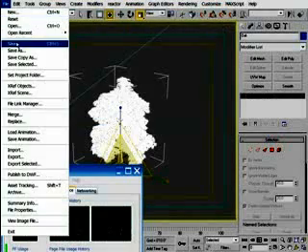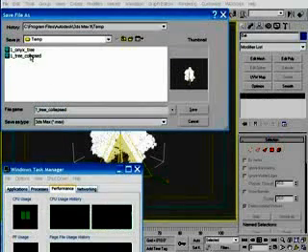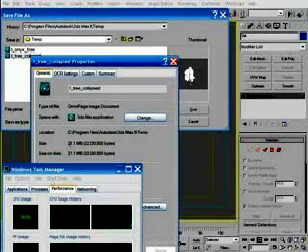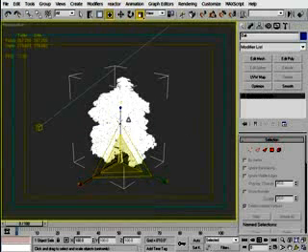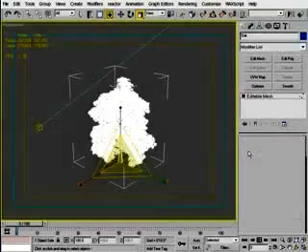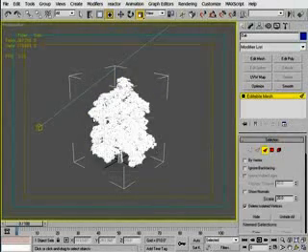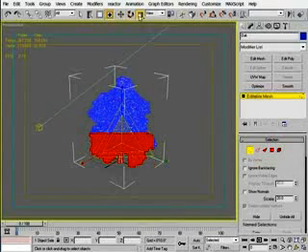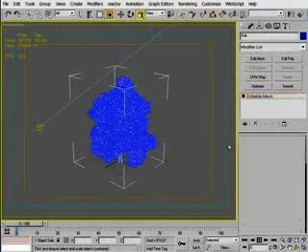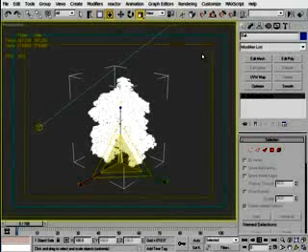Now if I go to the save folder and look again at the file size of this scene, I can see that the file size is now over 21 megabytes in size. And the reason that this scene generates such a large file size is because Max can no longer define the tree structure by algorithms or formulas. Instead, it has to store the X, Y, and Z value of every single individual vertex and face and all the other sub-objects for each of the three transform types: position, rotation, and scale. So for an object with 267,000 faces, it's pretty easy to understand why the file size is 21 megabytes.